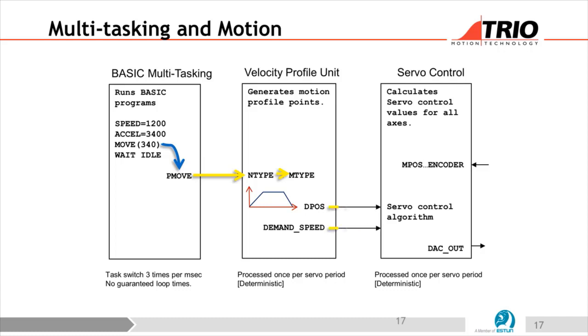I would imagine you've got 21 axes, but you've not got 21 workstations around that. So for the number of programs you need to run, I would suggest you're running 1 program for each action, each station. But maybe there's 10 stations. Yeah, some have 1 axis, some have 2 axes, whatever. Exactly. And everything coordinated by 1 main program that's doing the main sort of transfer timing. They're running at the same time, but should be in different tasks like that.